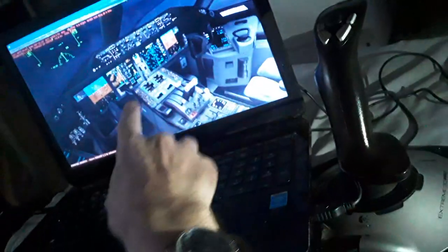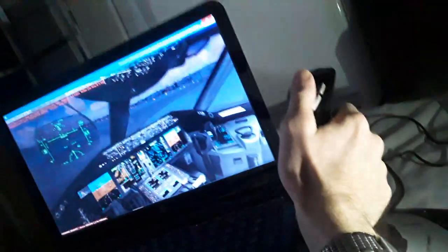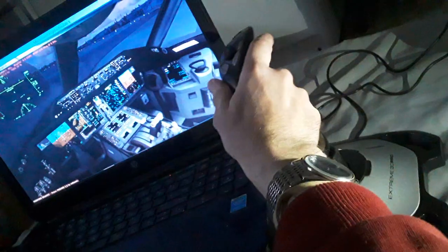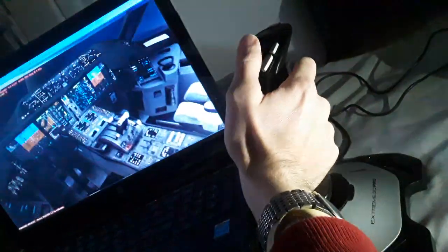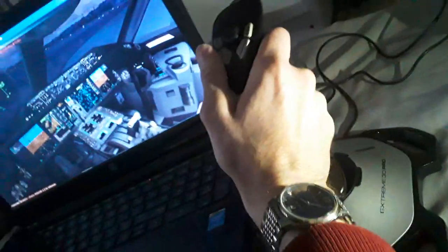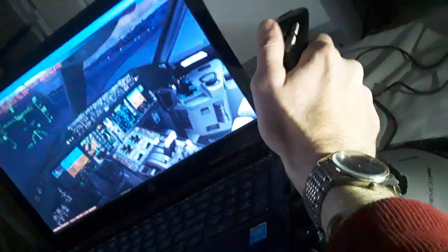Also the captain and the first officer flight controls in the Boeing are moving together. The yoke, the control wheel and the rudder pedals, they are interconnected. Unless you have some failure or you need to apply force from either side to override either yoke. Also in the Airbus you can use the side stick priority button over here, and the autopilot disconnect button.